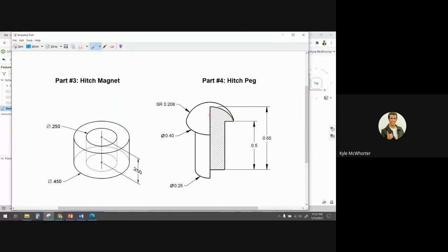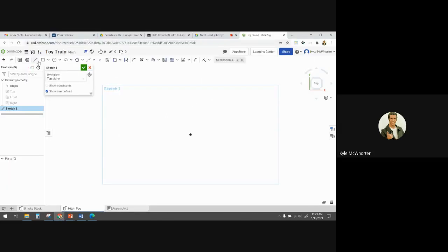So I need one curve and I need some straight lines, right? All right, so I'm going to get my line tool. Make some lines. Okay, those are the straight ones. And now I need a curve. I'll click on that vertex and then that vertex, and then just place it somewhere. Now you've got to be careful you don't accidentally put a constraint that you don't want, so you don't want anything lighting up yellow. So I will just place this somewhere random like that.